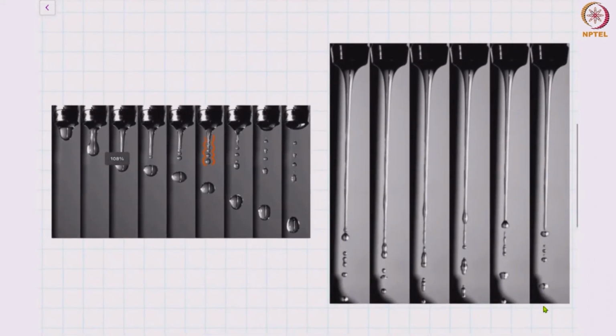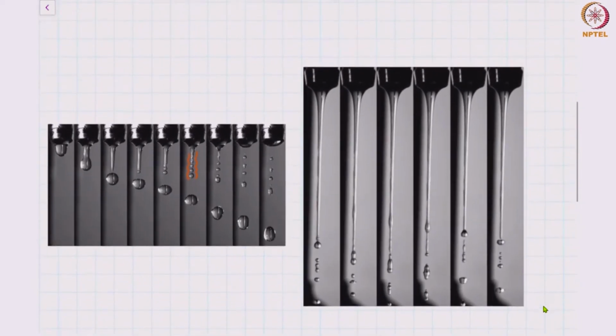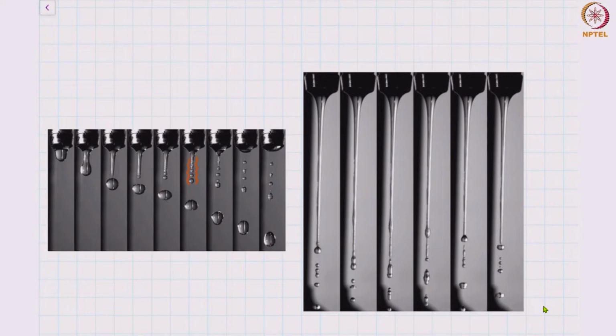But if you were to increase the flow rate sufficiently, then there will be a point where you have a stable jet, which eventually breaks up into droplets. Now, there is another interesting thing to note here, that you have an undulation somewhere in this region, and this undulation goes down. As the jet descends, this undulation is carried forward, but at the same time it's growing, and it grows even further. It's becoming a lump here, and then a droplet, and here it's detaching from the thread. So this process continues, and what you're seeing here is the Plateau-Rayleigh instability, or the Rayleigh-Plateau instability.